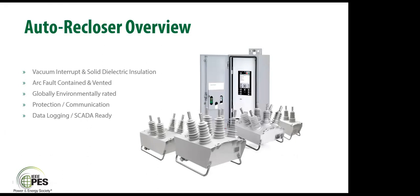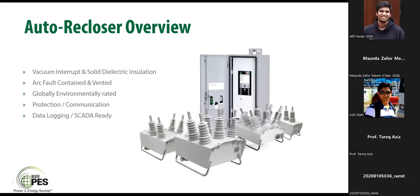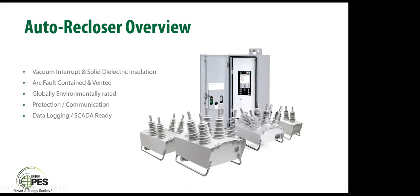Okay, so our topic today is directional protection, and it's one of the protection features provided in an automatic circuit recloser. Here you can see the overall view of an automatic circuit recloser, ACR. It has basically two parts. There is an external part, the tank, which you can see at the bottom, and there is a box, which is the control system. It's sometimes placed in the substation, sometimes on the same pole, just a bit under the tank.